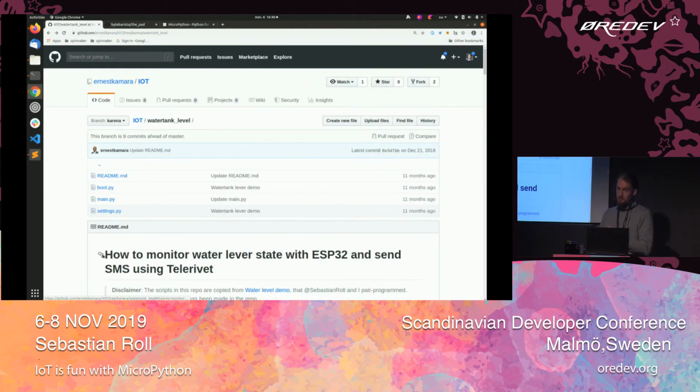Now in MicroPython, there are two special file names, two file names that are treated differently than everyone else. The first one is boot.py. This will run at boot up immediately, even before it establishes a connection through the USB. And after that is your main program, main.py. This is where you put your master code. And you can import other modules from main.py, but these will be run.